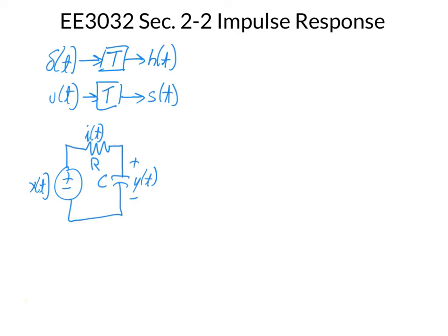So we can write the voltage equation for the circuit. If we look at the current, it's going to be the capacitance C times dV/dt, the capacitance times the derivative of voltage. So that is our current flowing through the circuit at any particular time, because the current through the capacitor has to be the current through this entire circuit.